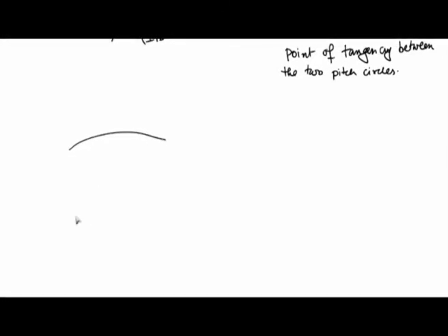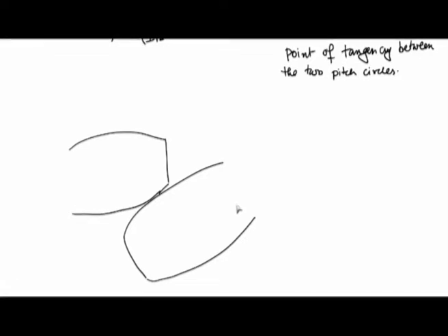Please understand, if these are the two gear teeth which are in engagement, at an arbitrary point during the time of engagement, at the point of contact, we look at the velocity of the point of contact. As usual, I will call the two gears body 2 and body 3. This is the point of contact, which I will call C to make it quite clear that this is not the pitch point.